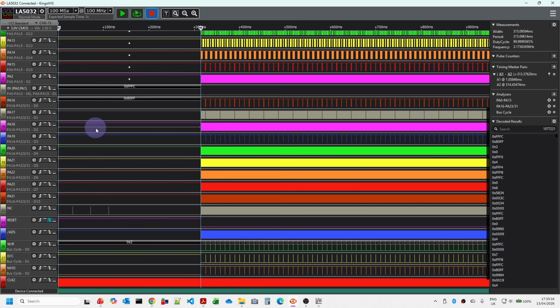So we can see there's not really very much going on. And on the address bus, we can see that the lower address has got FFFC. The reason we have that is because the A0 and A1 aren't enabled here, they're 0, and that would have made it up to F if those were there. And the top address lines, A16 up to A23, are all 1s.